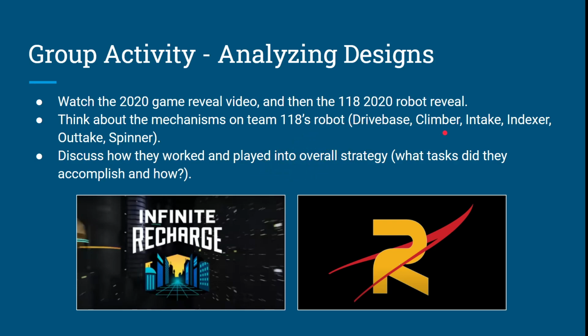And then finally they have their climber, which basically was a telescoping nested climber, and they have one of them on each side of the robot, and they extend that climber. There's a tape measure type thing inside so they can shoot it up and then pull it down, because lowering the climber is what needs to be strong, because you're raising the whole robot when you do that. Extending the climbers upward doesn't really need to be that strong. And those climbers are nested continuous climbers, so they're powered by a motor, and that motor raises the whole thing up and then pulls it down once it hooks onto the bar.